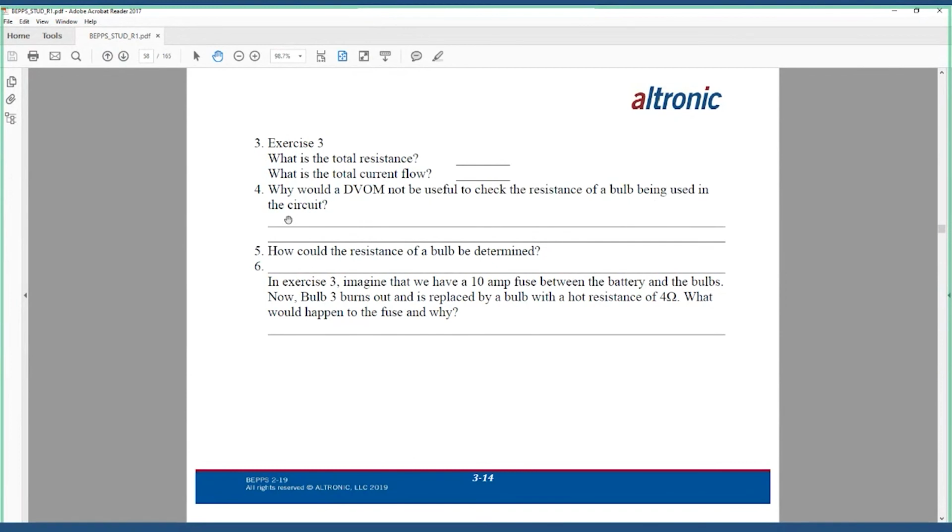Was the bulb on? Well, now back to fundamentals from last week. We wouldn't want to be measuring resistance of a circuit if there was power applied to it. Right. Okay, so I'll fill in some pieces here. If we measure the resistance of the total circuit, we should get 1.9. That's what our math agreed to, right?